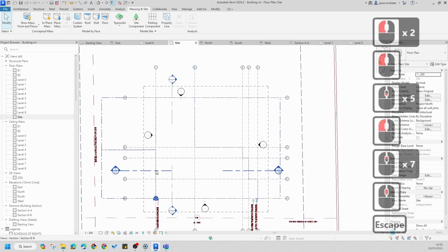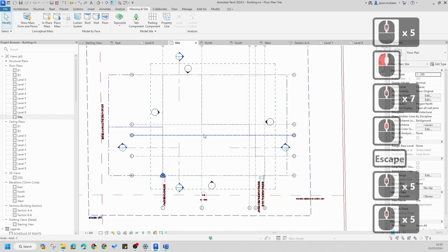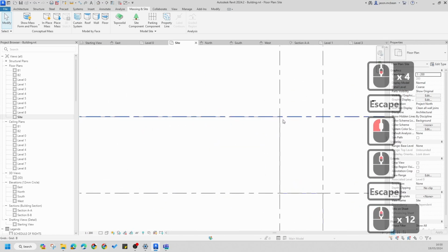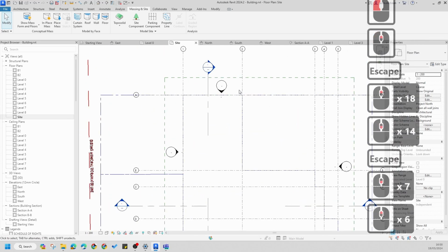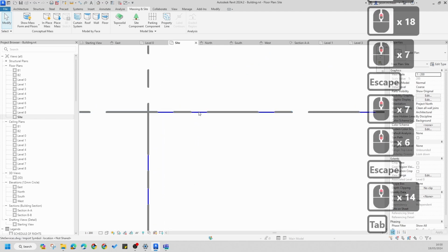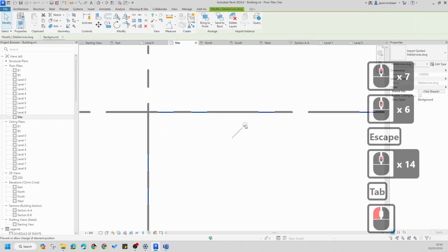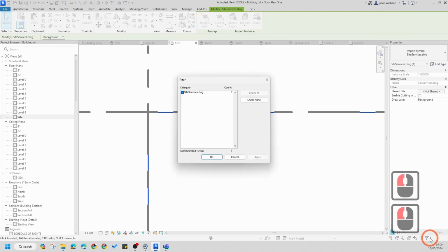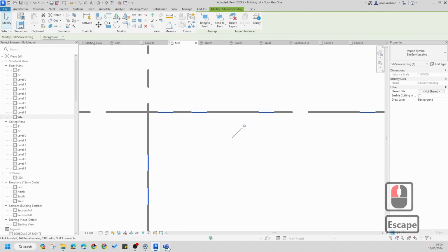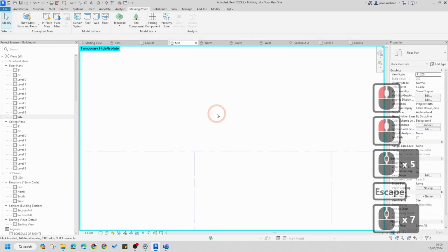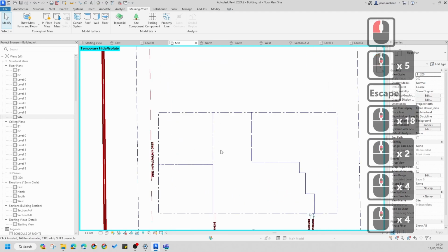Now I'm going to simply start drawing an outline of my building. So remember, our building outline will follow. I can switch this on again so I can start seeing where those blue lines are, where my site boundaries are. Okay, I can also select tab and select the site information. Remember, I can pin it now, so I can select the linked file. You'll see that it's the linked AutoCAD file, and I can isolate just that information. So isolate element, so it's basically temporarily hiding everything else.